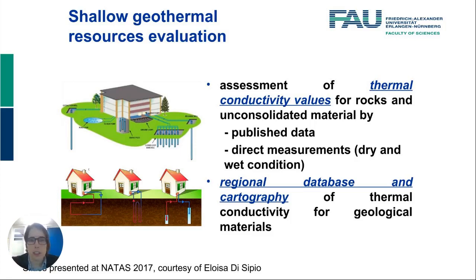Specifically, her work was looking at shallow geothermal resources evaluation and the assessment of the thermal conductivity values for rocks and other unconsolidated materials, both by reviewing the published literature data, and also looking at direct measurements in dry and wet conditions. That's especially important when you're dealing with unconsolidated materials because moisture content will have a very large effect on the effective thermal conductivity of unconsolidated geological samples.